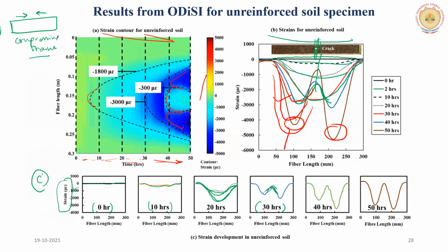After that, for some specimens, we observed that the optical fiber broke, like you said, there will be some maximum limit to it. But since this was just for experimental purposes, we did not jacket this fiber. In the field, these fibers are not placed bare in the soil.